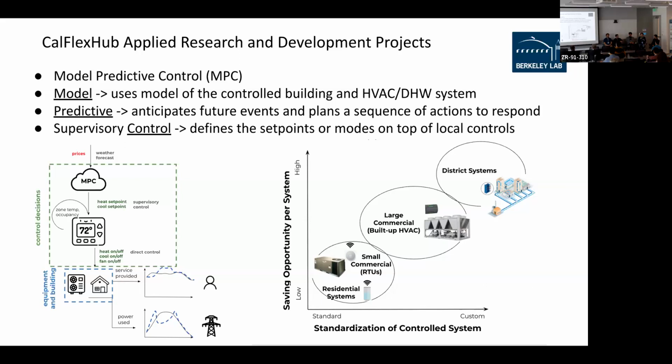So we capture the physical characteristics, and the other missing part, if significant, can be captured by another black box model, which I'd call a hybrid approach. But if not, then we can just go with the gray box model, and the MPC's disturbance rejection algorithm can keep updating the current state, so that we can at least guarantee the MPC's performance in short-term peak demand coordination, etc. It's very light and scalable modeling.